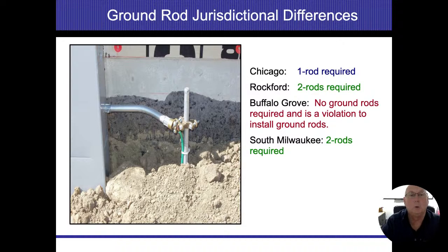And now the wire goes down into the earth, and it's going to connect to another one that's going to be about 6 feet away. I just think it's a great idea. There's nothing bad about having too many connections to the earth. We just don't want to have different connections to our electrical system at different locations. We want to keep all those separate, or all coming from the same point, basically.